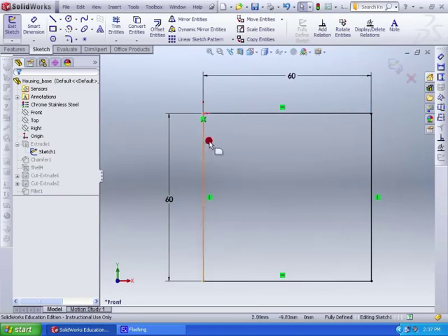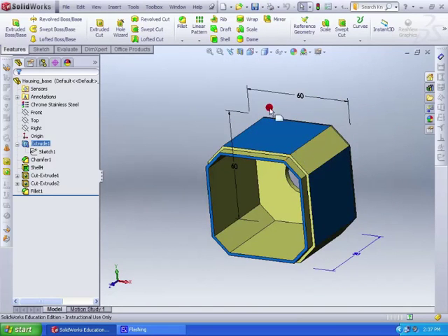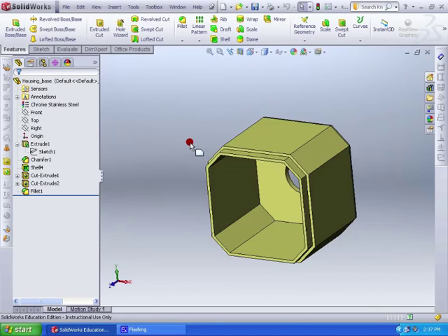So these are smart dimensions. We've used them to define our sketch, and all of the smart dimensions used to make this part and the feature thicknesses and so on will be generated for us. So when we create a drawing, we will generate those.